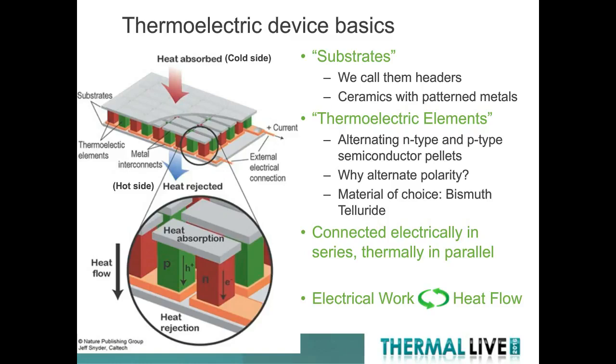The thermoelectric elements are a semiconductor-based material that in the direction of charge flow also creates a temperature gradient and heat flow. So with that thermoelectric device, as you apply current, the top gets cold and allows you to pump heat to the other side of the device.